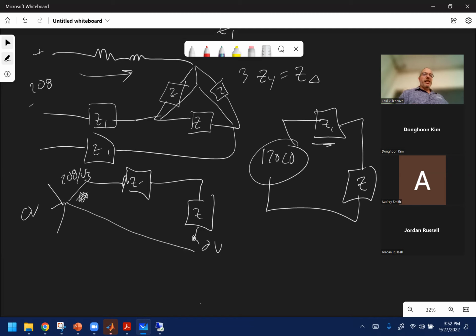And the reason why you did that again is because this voltage here is at 0 volts. Then you could say this voltage here is at 0 volts, and you can draw that common connection because they're electrically at the same point. Now it's just a simple series circuit.